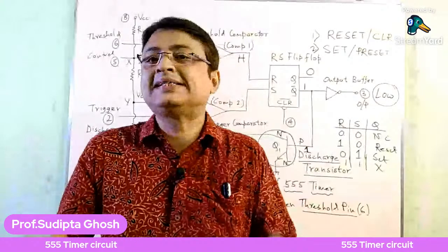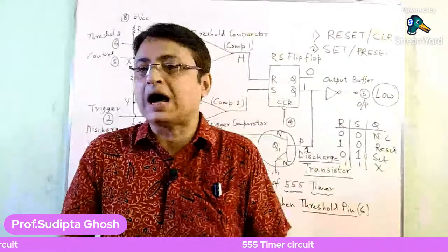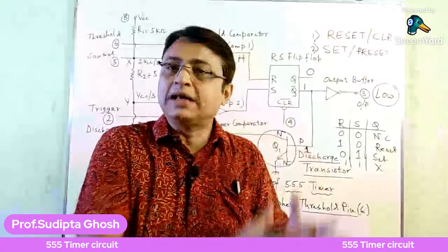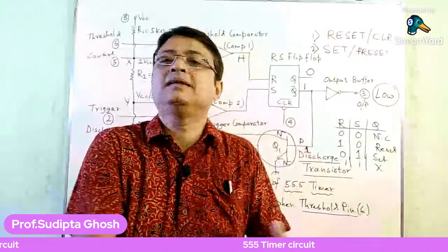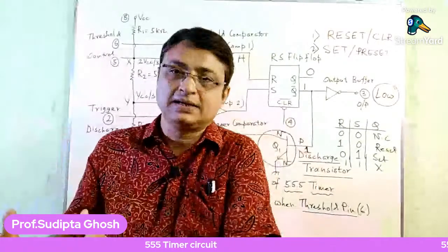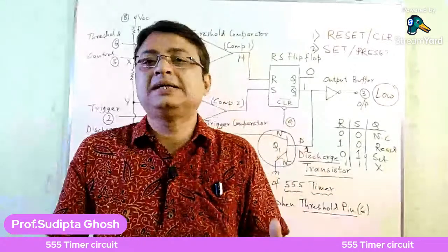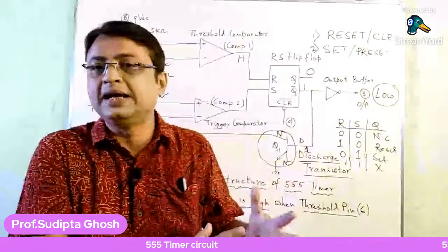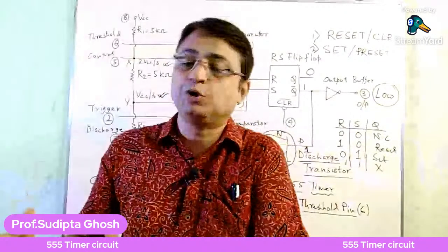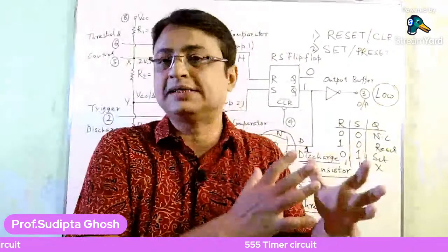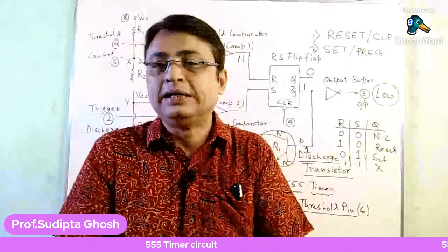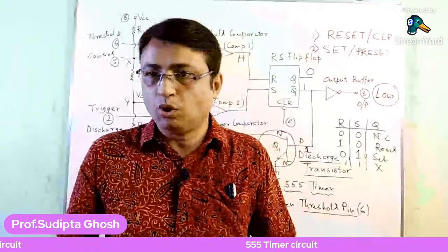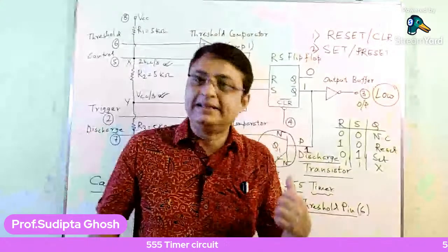When both the inputs are high, the transistor will be in the saturation region. If I consider a common base mode of transistor circuit, and the emitter base voltage is high and the collector base voltage is low, that means the transistor will be in the active mode of operation.